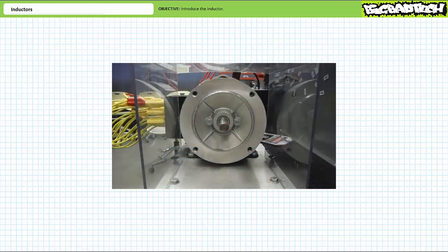Inductors, not so much. Inductors store and release energy from a magnetic field anytime there is a change in current and must carry current for that magnetic field to exist. The inductor storage and release process is necessarily a dynamic process. The only suitable analogy I've ever been able to come up with to describe the inductor storage and release process is that of a flywheel.